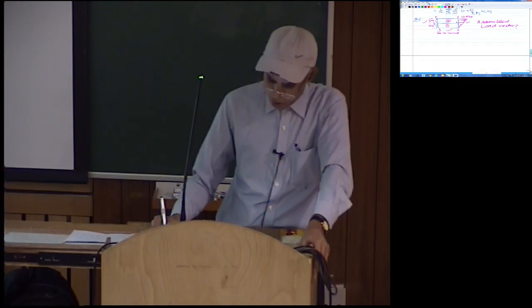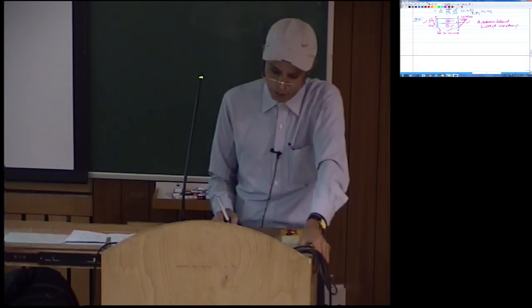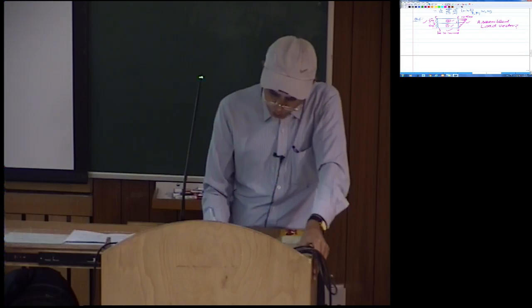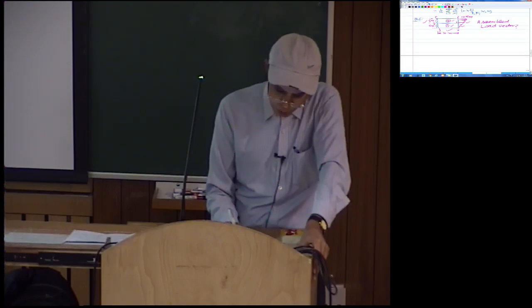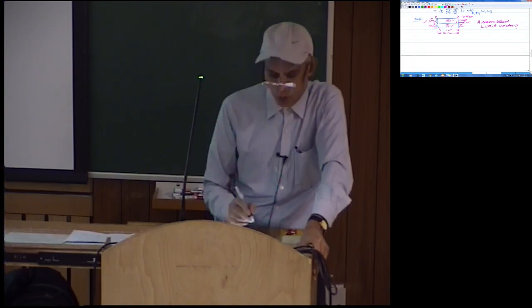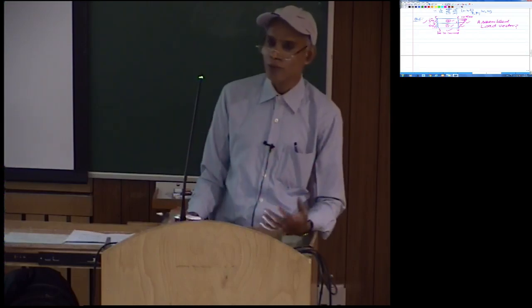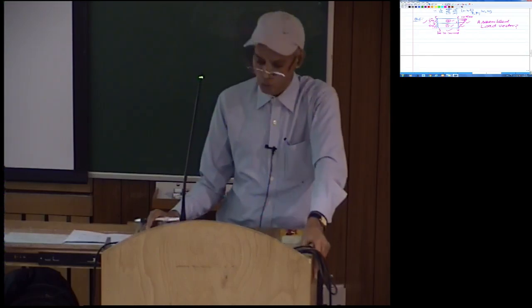Now the assembled load vector will have a contribution from the first element and from the second element. In each element you have on one side this distributed force, and on another side you are also going to have distributed reaction forces on this edge. Of course the reaction forces are unknown, so you will have to keep them as the unknown forces finally.